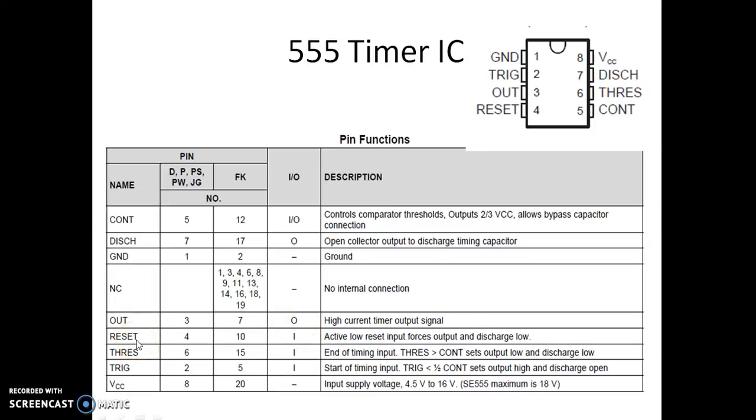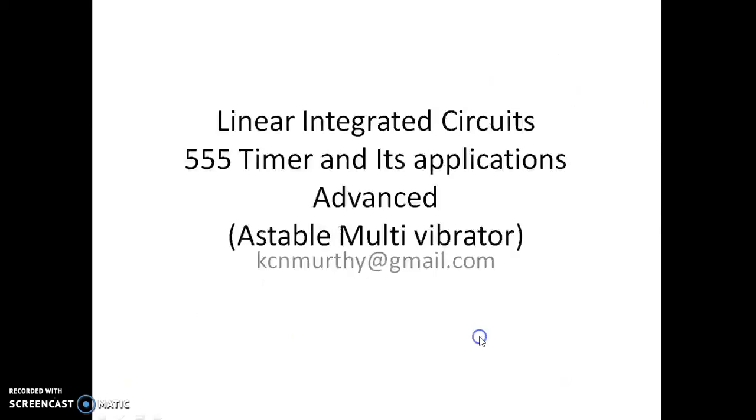And we have a reset. Reset is pin number 4. It's actually an input pin. It's an active low reset. Reset input forces the output and discharge to go low.